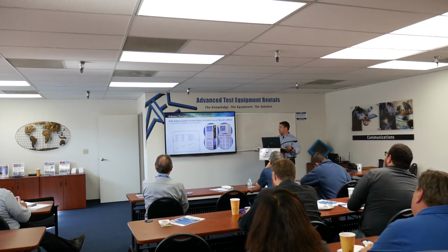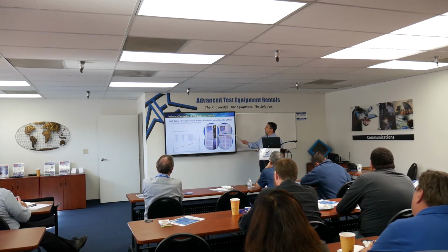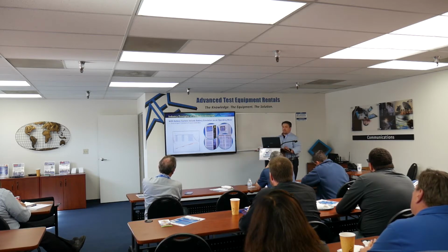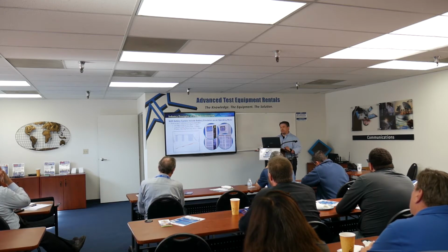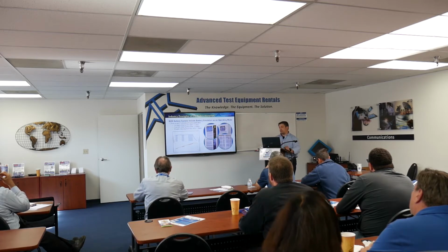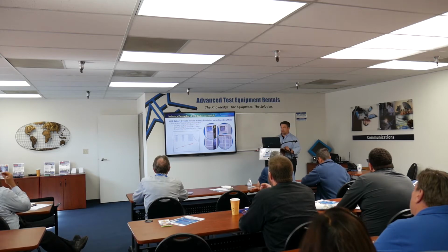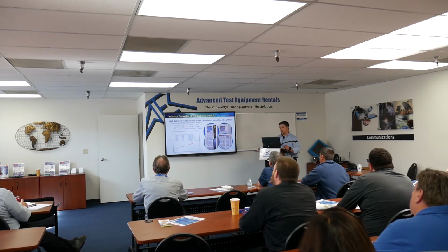And so here we have the 9200s and 9300s on the right. The 9300s are kind of like the big brother to the 9200s. These are built up in 100 kilowatt building blocks, and the 9200s are in 12 kilowatt building blocks. There are some ranges as well. The lowest voltage range is 40 volts, then all the way up to 1200 volts, and up to 1.2 megawatts by paralleling them.